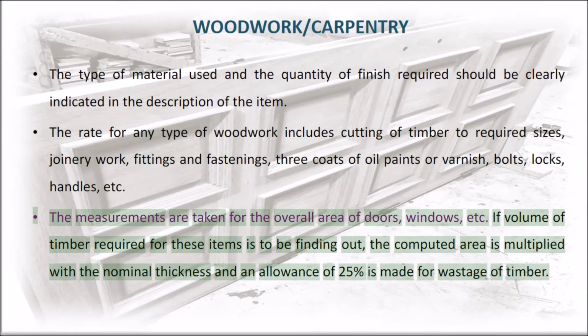The measurements are taken for the overall area of doors, windows, etc. If volume of timber required for these items is to be found out, the computed area is multiplied with the nominal thickness and an allowance of 25% is made for wastage of timber.